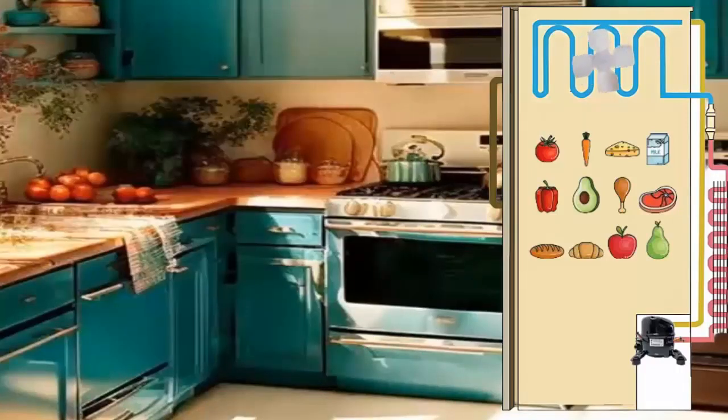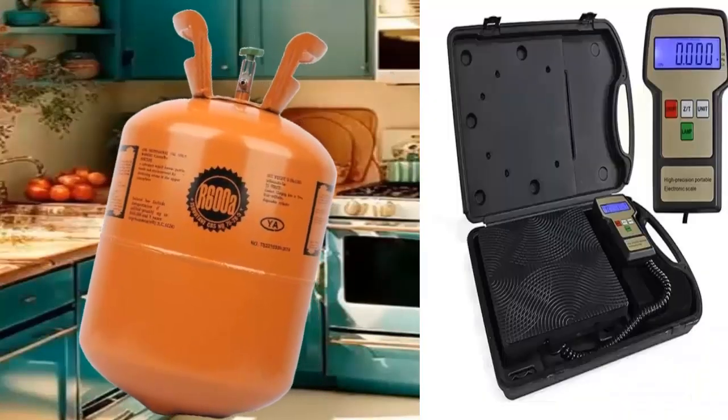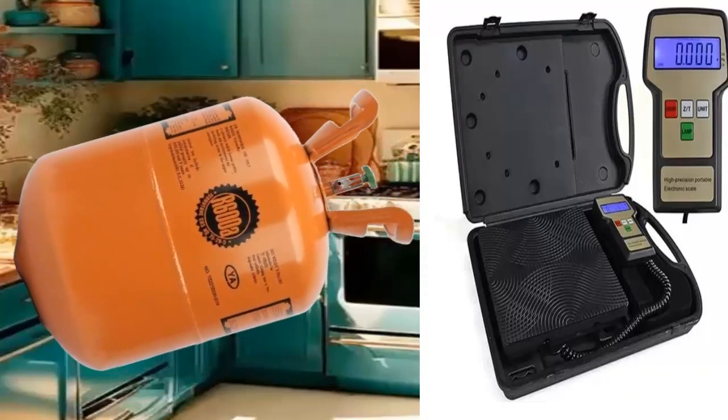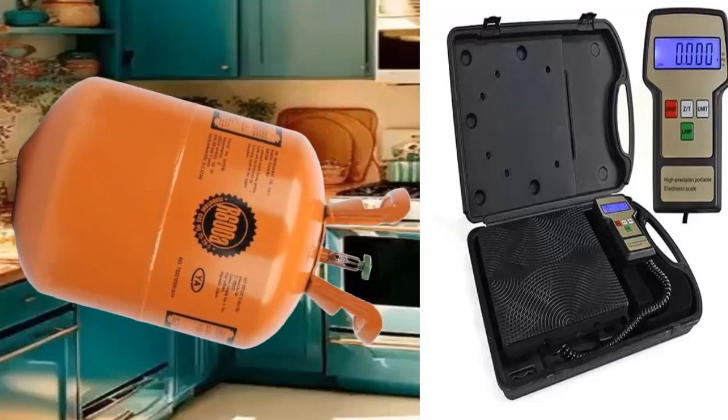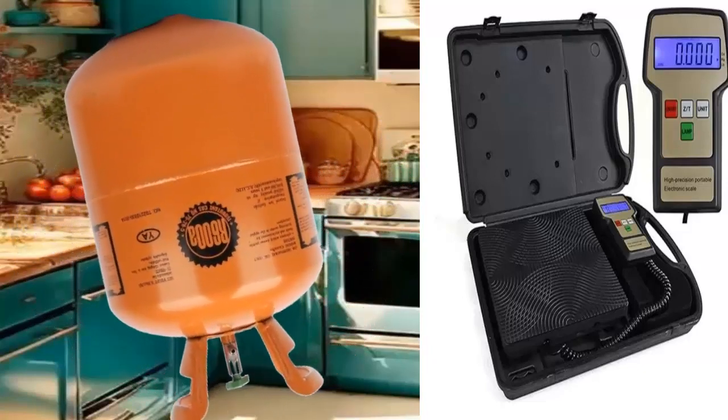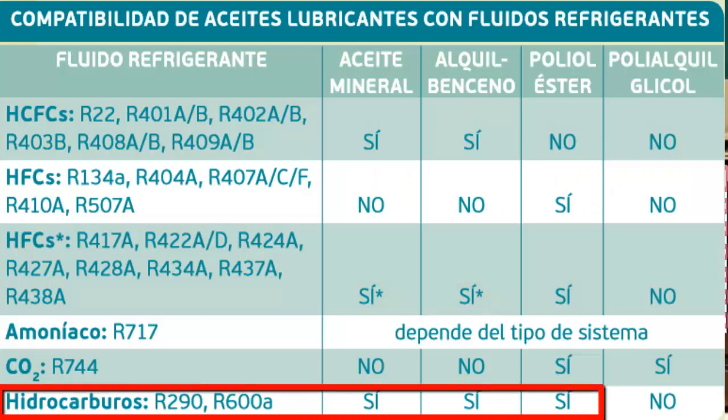The R600A, being composed of only one gas, can be recharged or introduced into the equipment in both liquid and gaseous phases, making it indifferent. The R600A is compatible with any type of oil. However, it is recommended to follow the compressor manufacturer's recommendations.